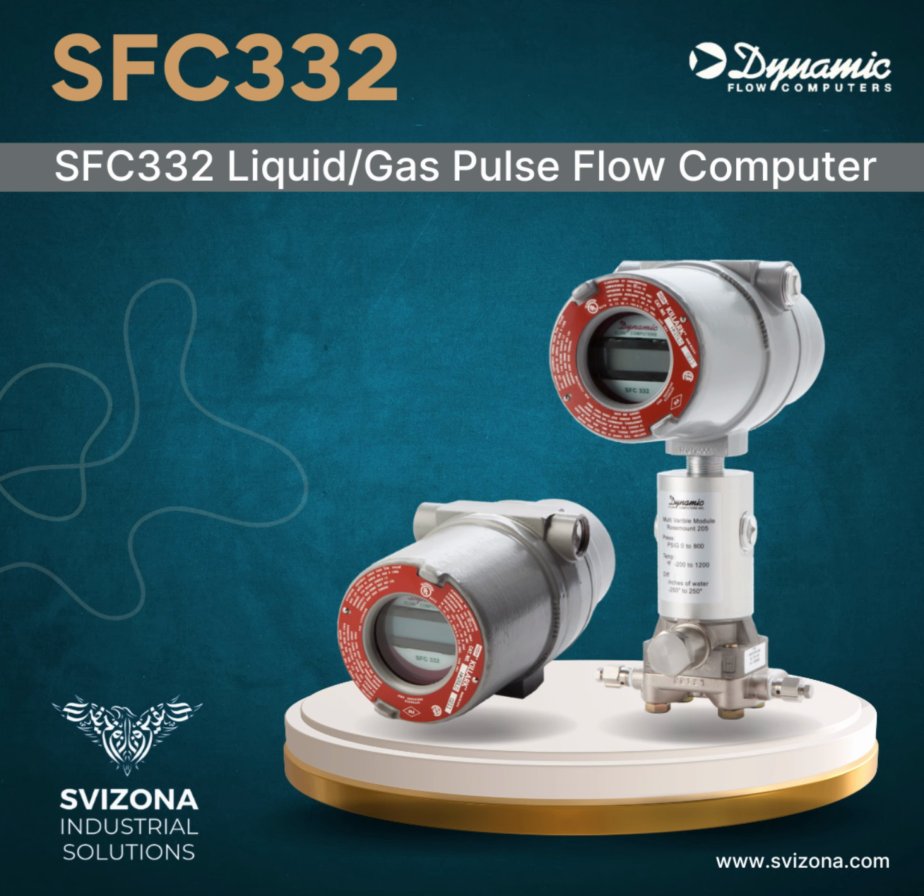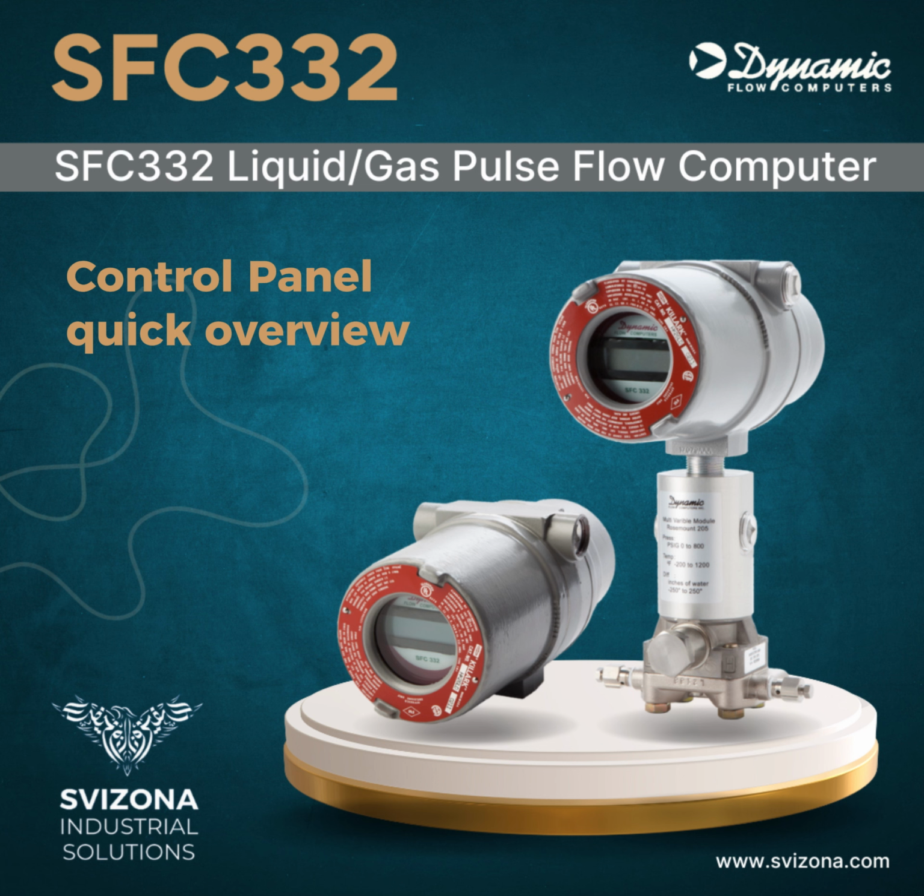For sure. Now, I'm looking at the manual here, and it mentions a bunch of different menus like tools, override, prover, meter, reports. Can you give us a quick overview of what those are all about? Sure. Those menus are basically how you access all the different functions of the SFC332. For example, the tools menu is where you go to set up communications, configure the meter, and even manage security levels. So it's like a control panel for the whole system. Yeah, exactly. And then you've got the meter menu where you can define things like units of measurement, set thresholds for alarms, and even determine how it calculates averages. You can really fine-tune it, customize it to your specific needs.